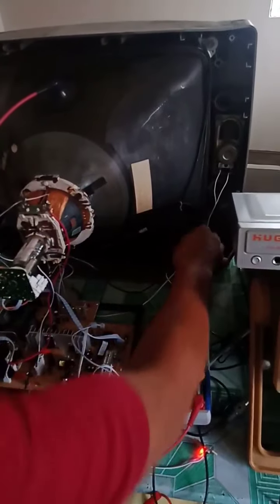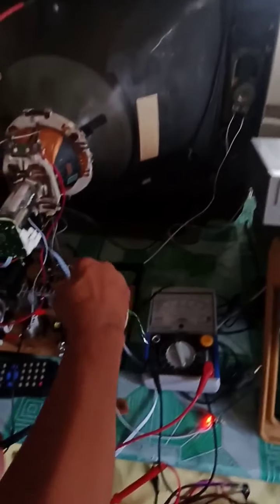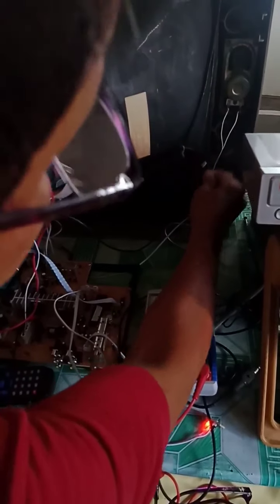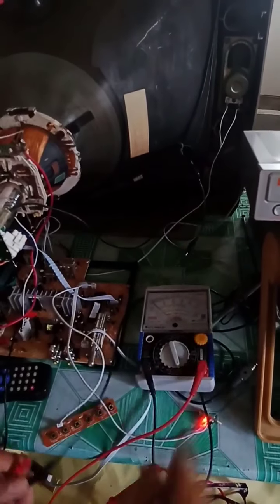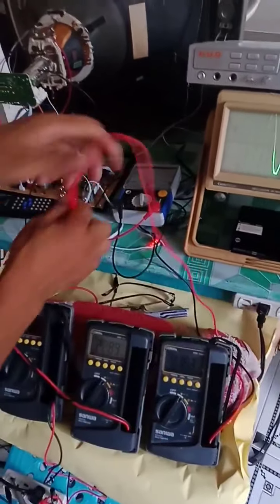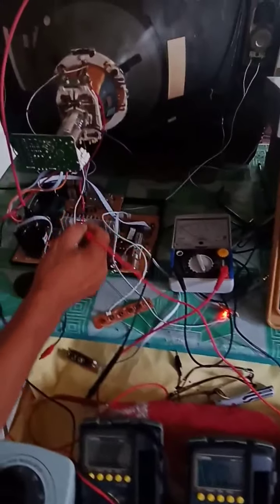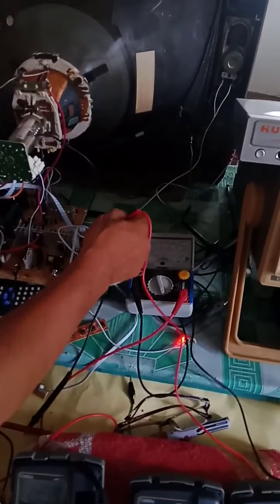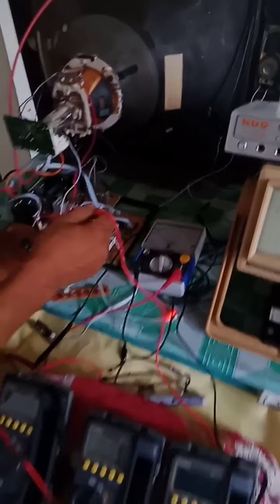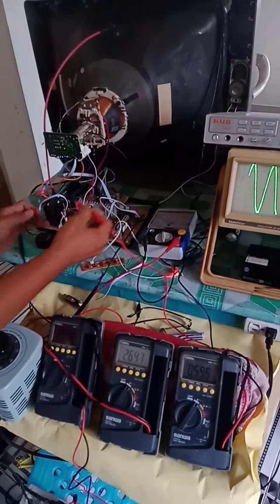Okay, you may connect it here, or you can connect this one here, or here, or here. But it is appropriate here because it is away from the circuit, but it is still the negative side. Connect the negative of the DC voltmeter to the negative side of the circuit, whereas the positive side will be injected to the electrodes of the transistors or terminals of the IC. Like for example this one, we will permanently connect.